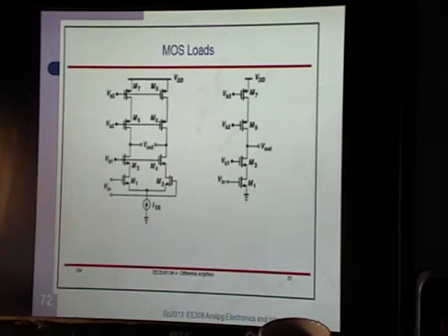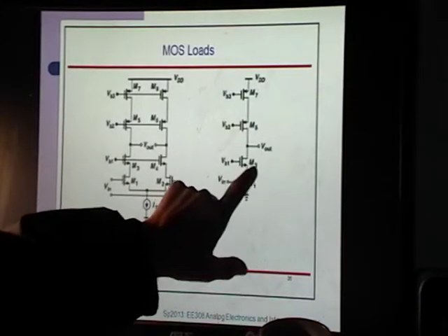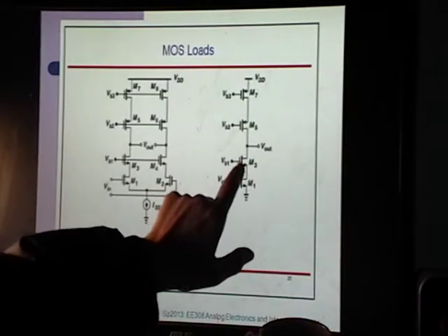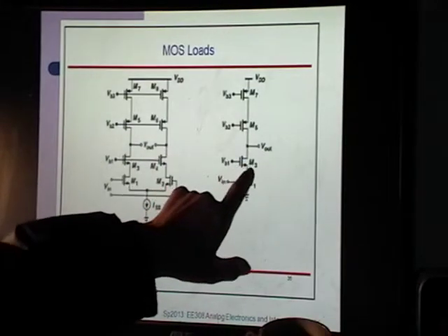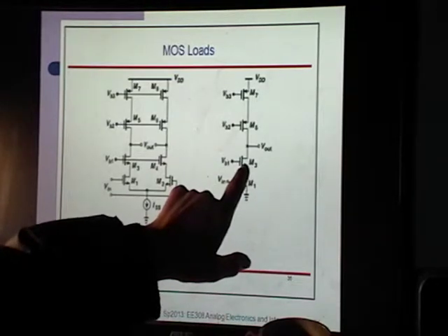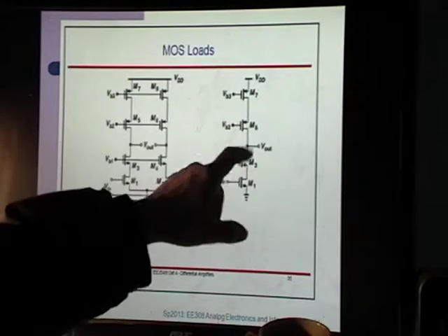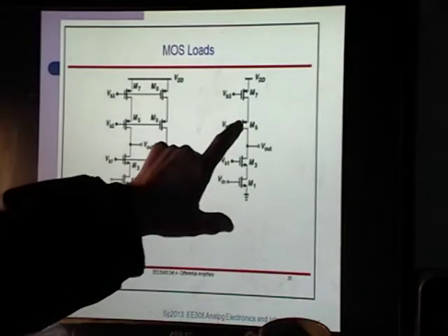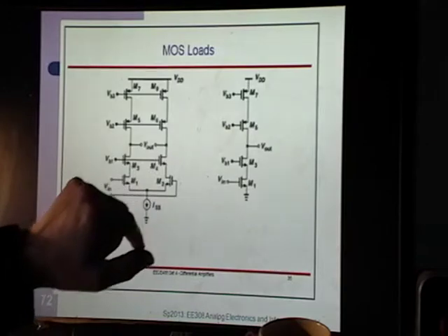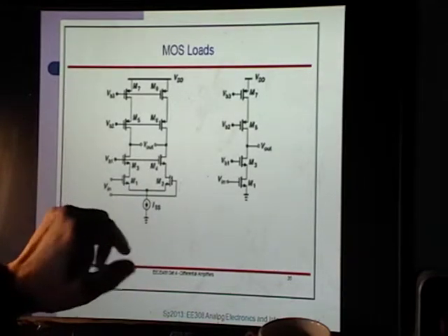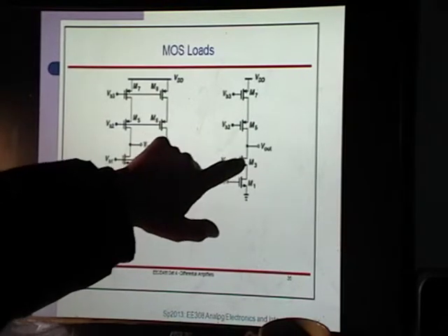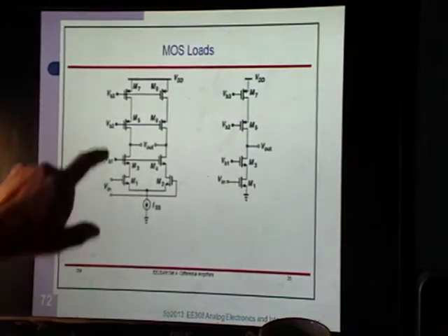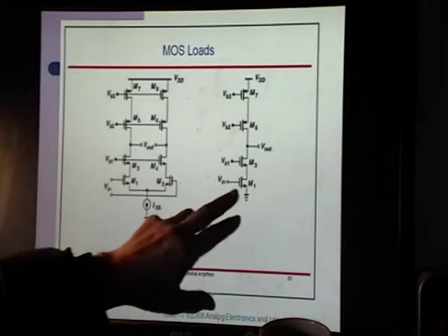Okay. And one term that I have not mentioned is, yes, it's RO squared, but it is multiplied by the GM of the second transistor. So the approximation that people use for this resistance is it would be small GM3 RO looking down in parallel with GM5 times RO, just GM RO squared. So one of these GMs actually comes out to a combination of these two, but GM RO squared.